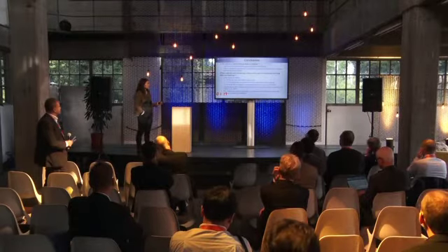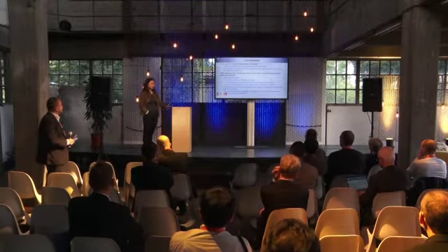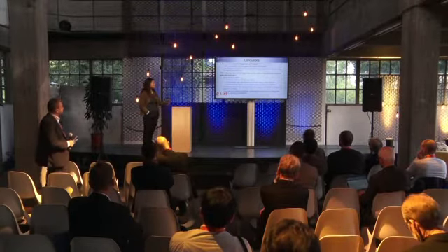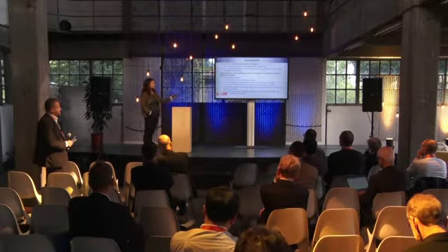In terms of composition, more than 90% of the debris is iron-based, 2 to 7% is highly concentrated in the cage coating material, and 2 to 6% is from external sources. The variation of the surface morphology on the sphere and the chunk and lamella debris depends on the traveling time of the bearings.